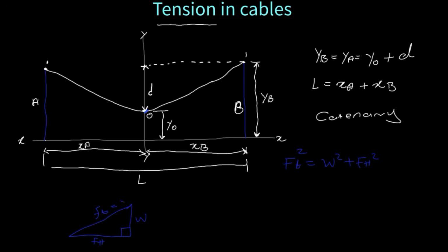Ft is equal to yb times W, and the W that I am talking about is not the weight, it is this one here, as the one that we have on this diagram. This is a small letter w, which represents the Newton per meter. This is the weight per unit length of the cable, and then this will be the total weight of the length of cable that we are dealing with.